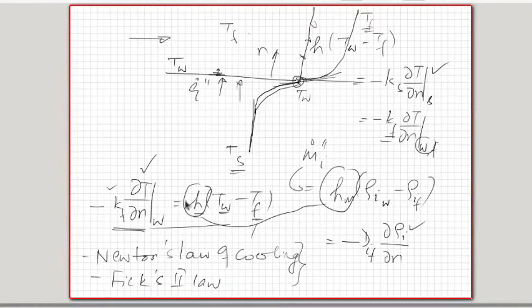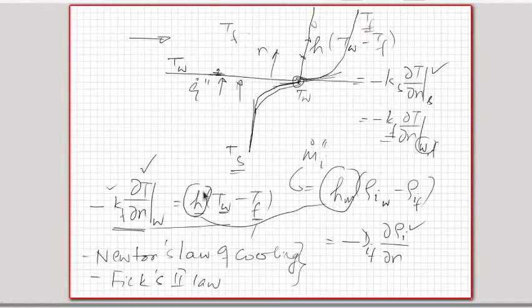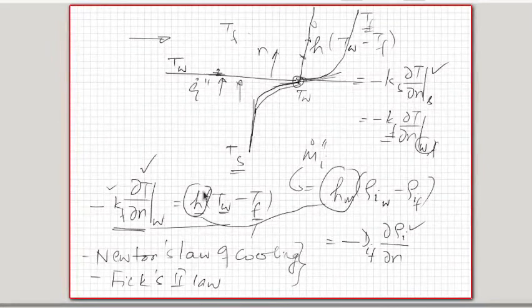So the heat transfer rate or the mass transfer rate are calculated using Newton's law of cooling, to use in the various heat balance or mass balance calculations. So this is the way it goes. You have governing equations, which are complex differential equations. You simplify them, you solve them either analytically or numerically, and get the temperature distribution or the mass fraction distribution or the partial density distribution. And using the gradient of that at the boundary, you evaluate the values of heat transfer coefficient and mass transfer coefficient and use that.